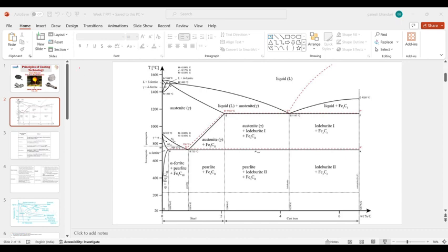Okay, so what you have to do is quickly cool down your sample from 750 degrees Celsius to a temperature of around 400 or 500 degrees Celsius. Then you are again going to put that into a furnace at 400 to 500 degrees Celsius and hold it for 1 hour or 2 hours according to the desired time, and then you are going to normalize it.